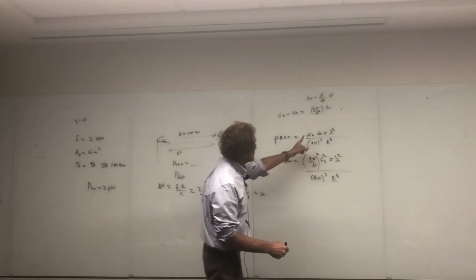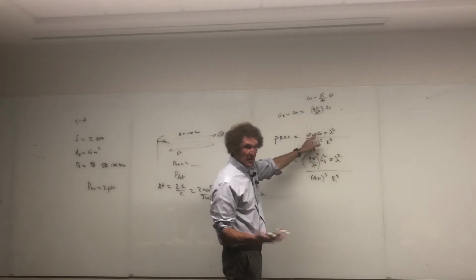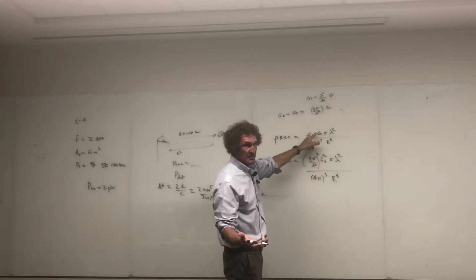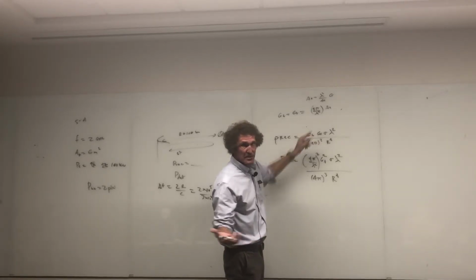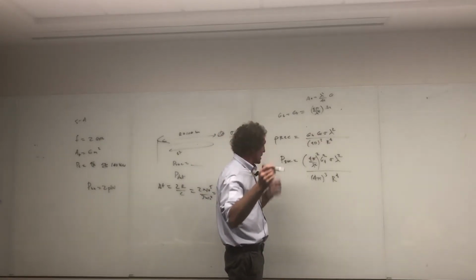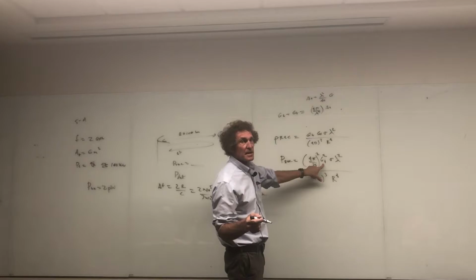It's gain of transmitter, gain of receiver, right? They're the same, so it's just this squared, gain squared, if you will. And gain is 4 pi over lambda squared times the aperture or area. Correct? Is everybody seeing this? You're looking at me. I have the gain squared, don't I? First gain times second gain, gain squared.